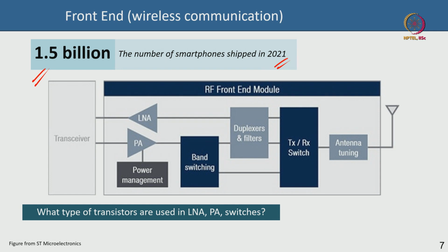Okay, things are becoming more stringent at the design front, and so it is all the more imperative for us to appreciate what devices are used and how we can improve the device, because only an improvement in the device leads to a disruptive improvement in the systems technology. For instance, gallium nitride was a disruptive technology that has pushed gallium arsenide more or less out from the really high power segment at moderate frequencies. At very high frequencies we still have indium phosphide, but LDMOS and gallium nitride are the dominant competing technologies for wireless base station power amplifiers.